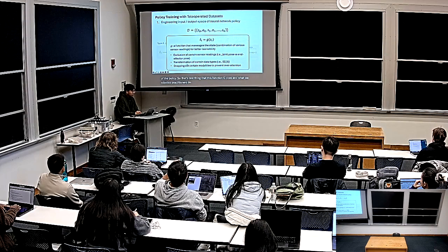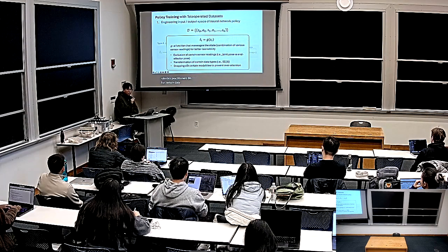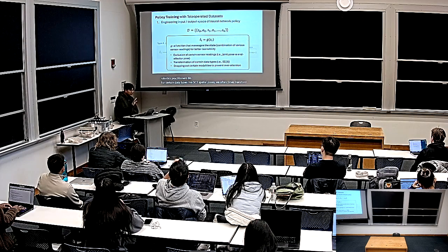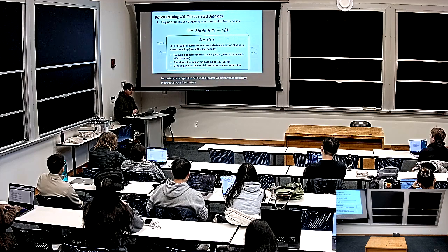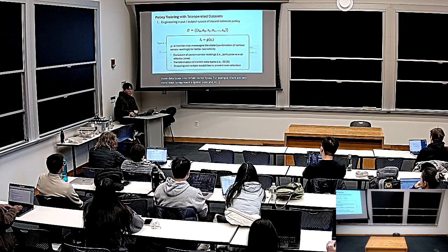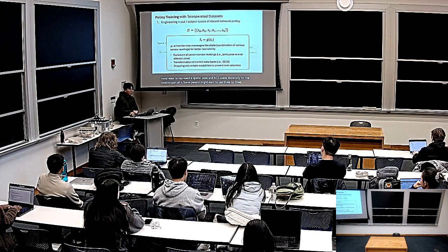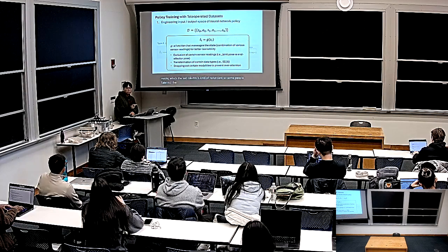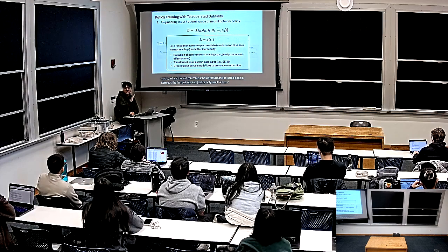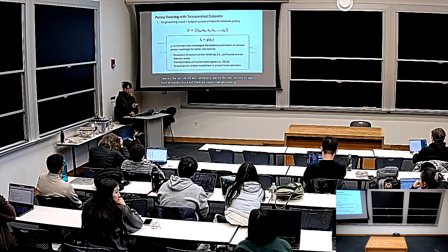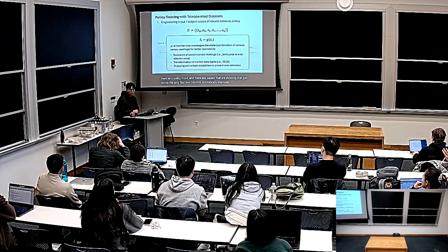And for certain data types, like SE3 spatial poses, we oftentimes transform those data types into certain vector types. There are many ways to represent a spatial pose in SE3 space, especially the rotation part of it. Some people might use a 3x3 rotation matrix, where the last column is redundant. So some people take out the last column and only use the first two columns as a policy input. There are papers showing that taking only the first two columns dramatically improves the policy learning performance.